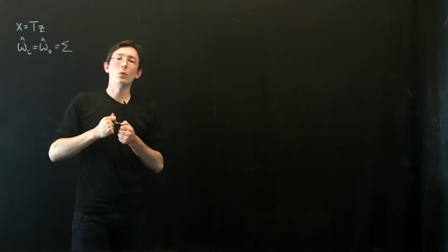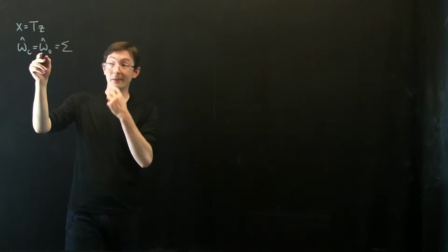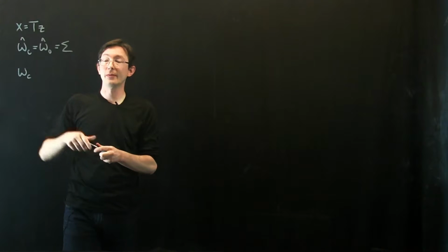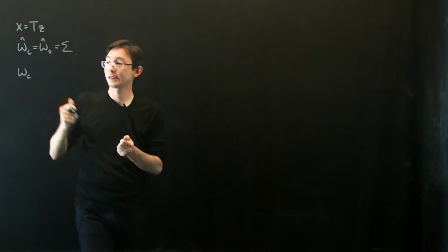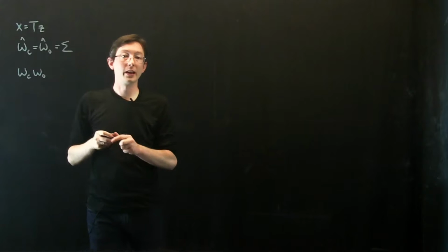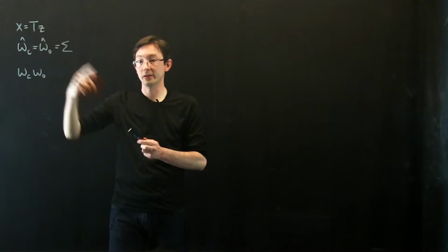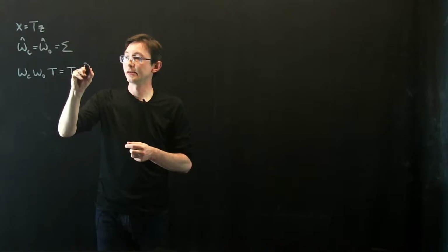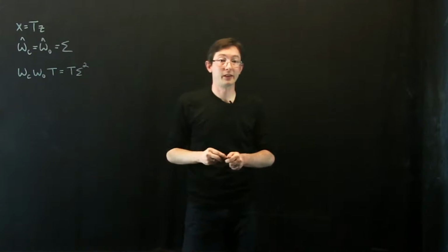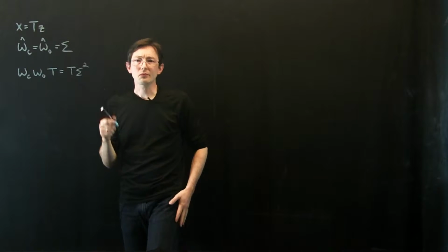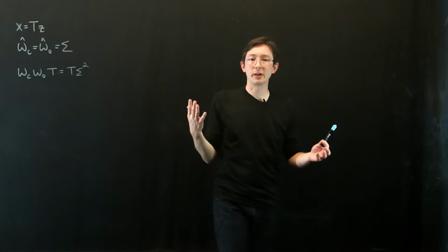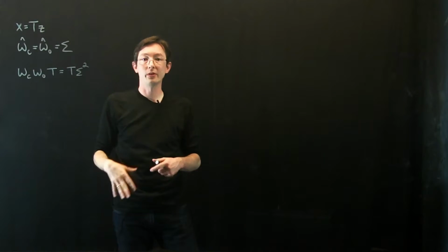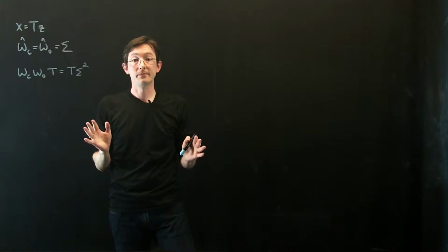And if you remember, one way that you can derive this T transformation is I could take my controllability Gramian from my original system in my coordinates x times W_O, again, my observability Gramian in my original coordinates x, and I could compute the eigendecomposition of this super big n by n matrix of Gramians. Now, it's super interesting math that you can do this, the balancing transformation. It's rock solid. We worked through it all. We coded it up. It works.